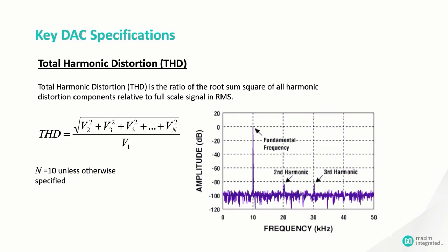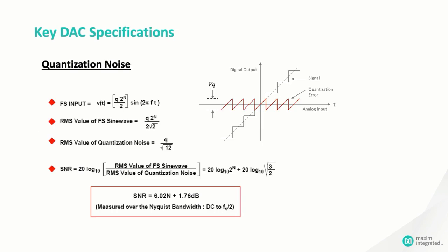But harmonic distortion isn't the only source of dynamic distortion. Think about it. When we quantize each sample, we're adding significant distortion right there by forcing a natural, continuous signal to assume discrete values at precise time intervals. Now, in the time domain, Nyquist gives us a useful rule of thumb that we have to generate output samples twice as rapidly as the highest frequency we want to resolve.